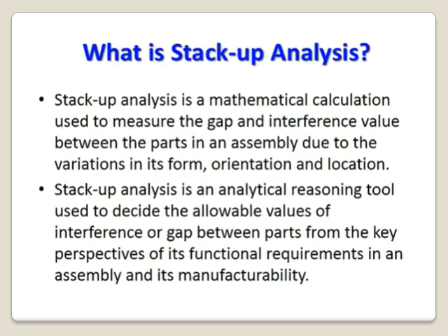Finally, from tolerance stack-up analysis, we can find how much interference a part can have, how much gap an assembly can have. This will tell whether it is a good part or a bad part.